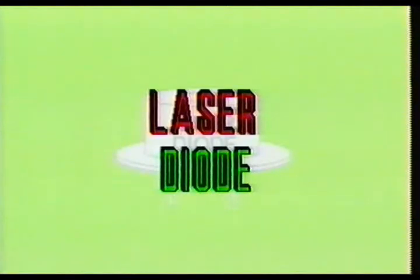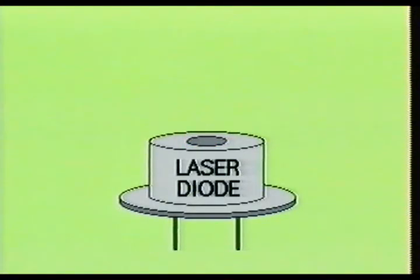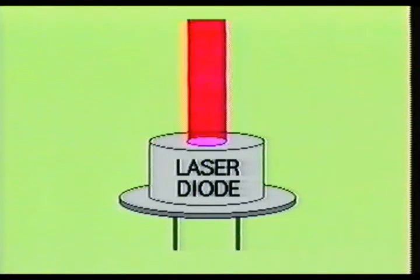In this portion of the video, you will learn about laser diodes and how they work. The laser diode is a semiconductor device designed to emit a coherent beam of light energy. Power outputs from these devices are typically about 3 to 5 milliwatts. The characteristics of the laser diode are determined by its chemical composition and its geometry.